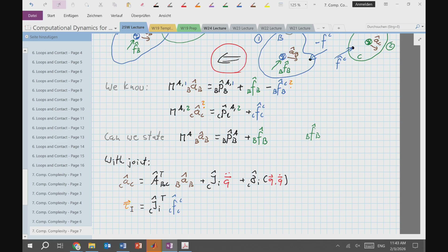Resolving a forward dynamic problem, tau is given, q double dot is not given. And there's a certain duality in these quantities, right? From the actual true constraint forces, I don't know the forces, but I know there's no motion. And for the active motion primitives, I know the force, or the generalized torques, and I don't know the acceleration.